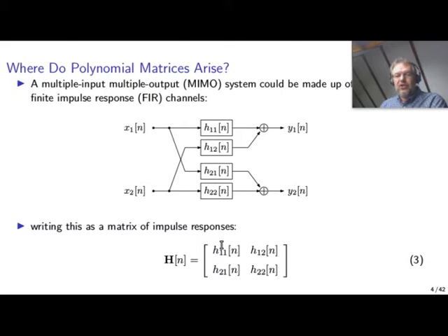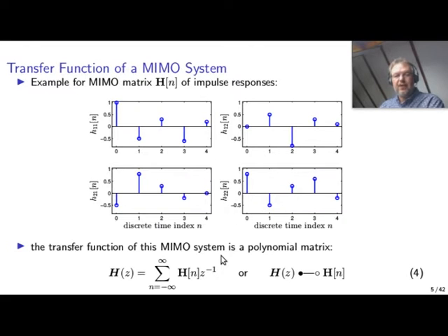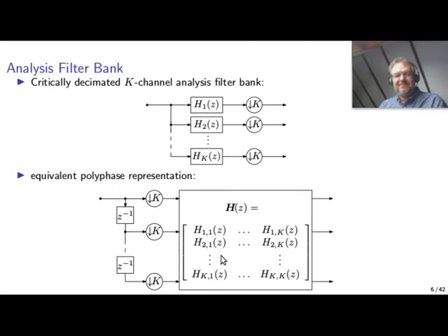And what you then have is a channel matrix that contains impulse responses and not just real or complex valued gain factors. So if you now imagine this, if you had a 2x2 matrix, then every matrix entry is an FIR filter in this case. And if you take a z-transform of this, we have a 2x2 matrix that now contains transfer functions. And this is your first polynomial matrix here.